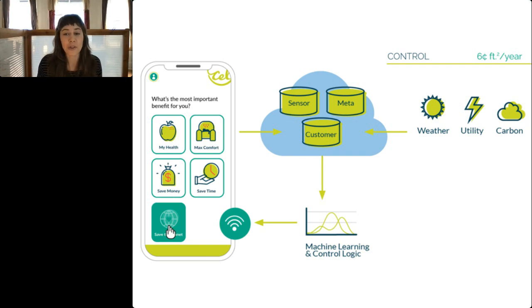So in these particular cases, what we're trying to do is to continue to update this physics-mimicking black box data-driven model to incorporate devices like water heat, to create a solution that's modeling the building and trying to optimize its operation, and learning more about how user preferences, the devices, and time varying rate signals interact in order to get better operational control. And operational energy in the life cycle of a building is 70 to 80% of that building's total life cycle energy use.